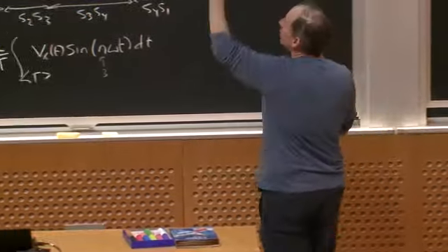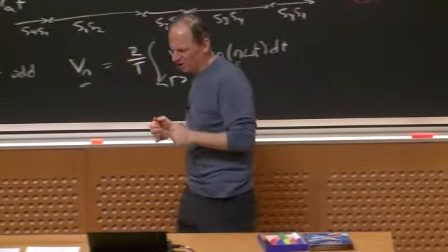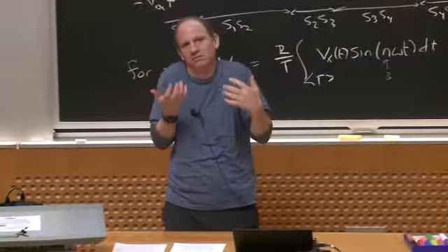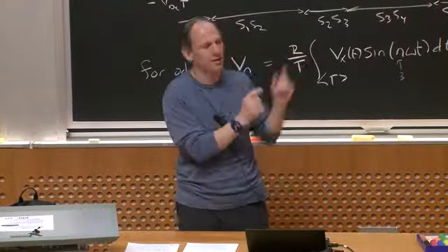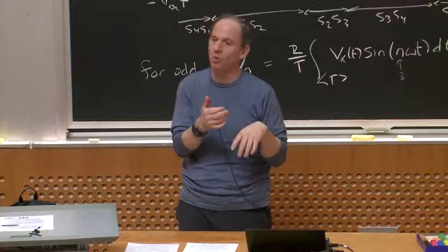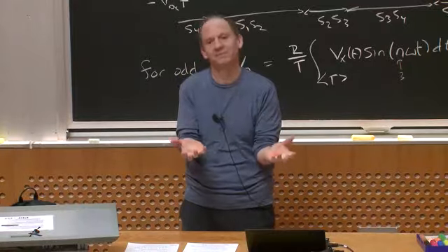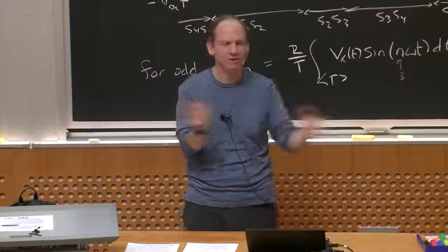Each time you put in 1 pulse in a half cycle, you can ultimately pick 1 harmonic to eliminate. And when we talk about 1 harmonic, we're keeping everything half-wave symmetric, so we care about 1 odd harmonic. Okay, so we're assuming our evens are all gone.